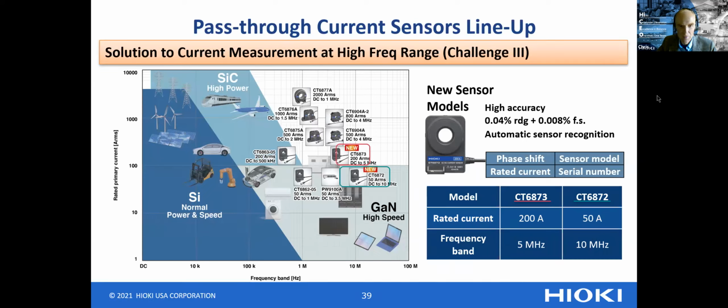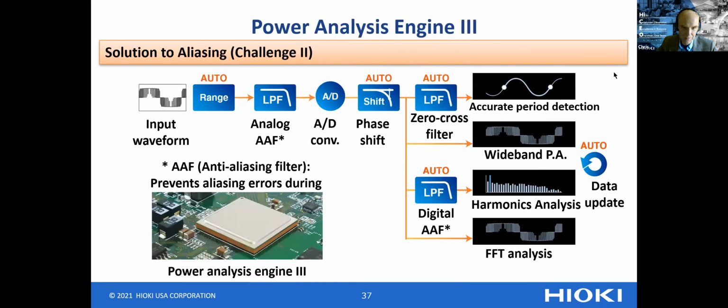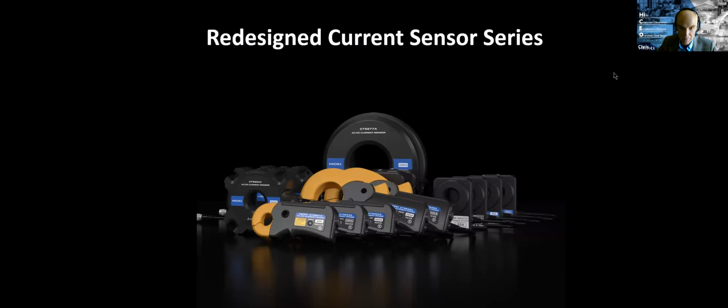So the first question: why is it so difficult to measure near zero power factor? A very small phase shift causes a significant error in the active power measurement. That is the correct answer. I guess most of you got that. And then, how many harmonics should you measure? Most of you think it's 5 orders, and that's the most common answer. If you're in research and development, you might sometimes want to capture many more harmonics. So I guess both answers are correct.